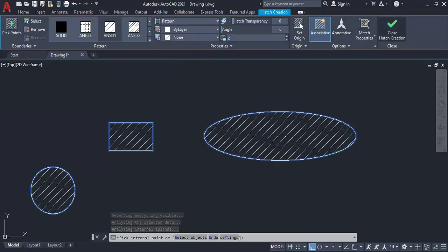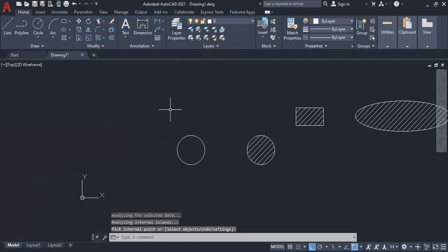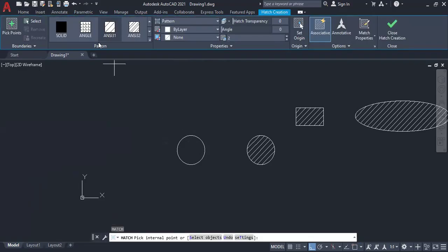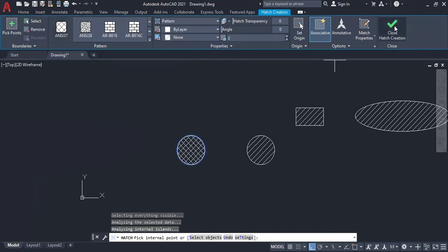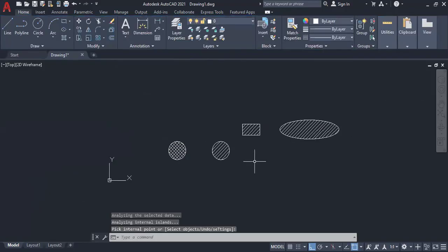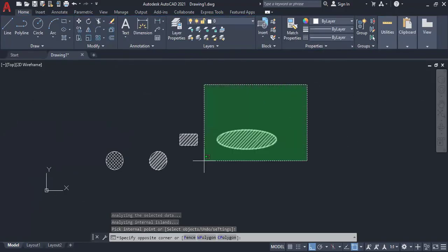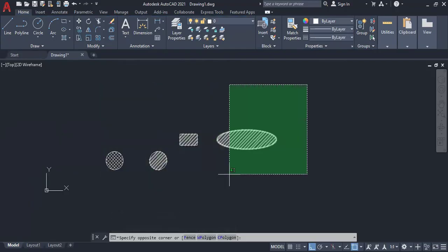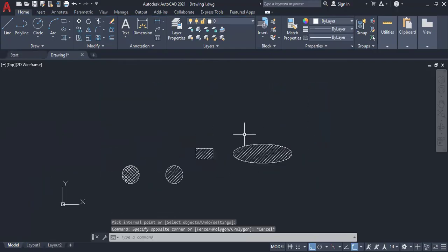For this, you again go to H enter. It will go to the hatch command, so you can select any of these hatches. This is how you can use the drawing commands in AutoCAD. So now you've done something. Okay. So now I'll move on to the modify commands.